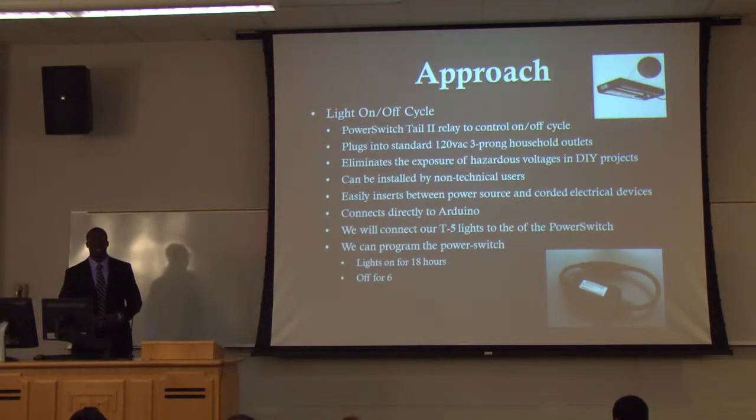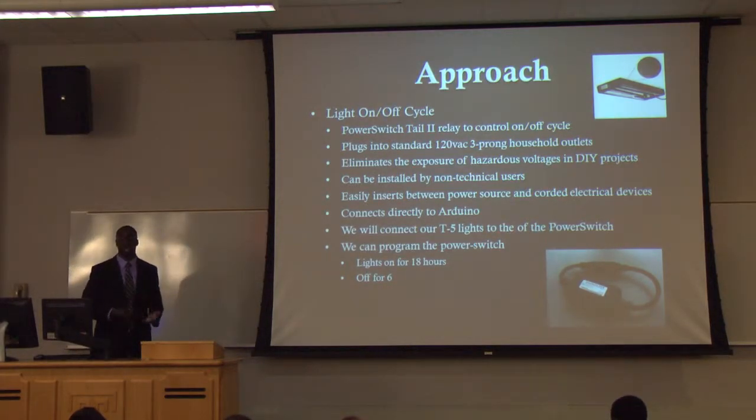So we'll be using a relay to control the light on and off sequence for our system. We're using the PowerSwitch Tail 2 relay in order to control the light, on for 18 hours for the lettuce and off for 6 hours. Just through talking to the aquaponic gardeners, they told us that this is sufficient lighting for the plants and will have our plants grow sufficiently.